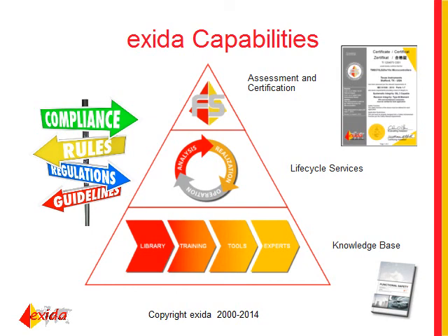We can take it from two extremes. On one extreme, if we've got a compartment around a gas turbine that's got gas piping in it, that's a relatively small volume. It's a pretty rectangular shape. We can put one or two sensors in there and get coverage of the area. It's closed in, with closed doors, so you're going to be able to sense if there's a leak.